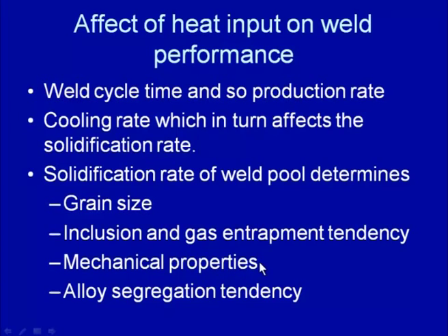Another important point is that the heat input also affects the alloy segregation tendency, because a higher heat input reduces the solidification rate, and a decrease in solidification rate increases the solidification time, which in turn will lead to a greater alloy segregation tendency.